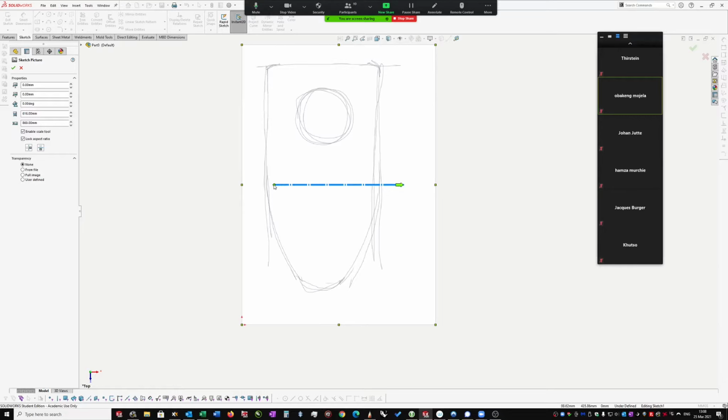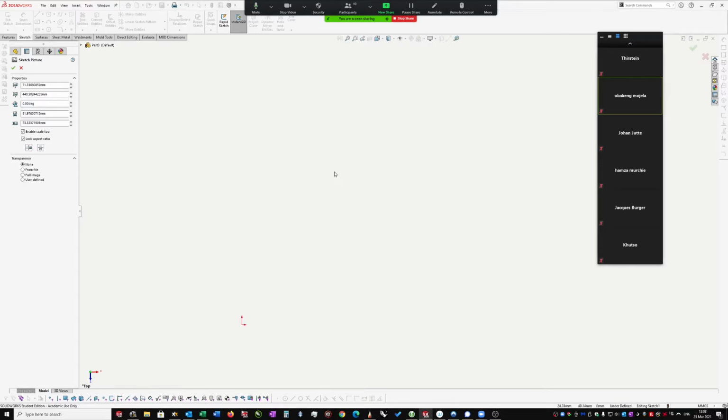So what I do is I grab the left hand side of the sketch, drag it to one side of the sketch, and then when I grab this other side and drag it across to the right hand side and let go, I'll get this sizing dialog box. So I'm going to type in here 30 and hit enter. Okay, my sketch has disappeared just because it scaled it, and you can see how far away it puts the sketch from my origin point.